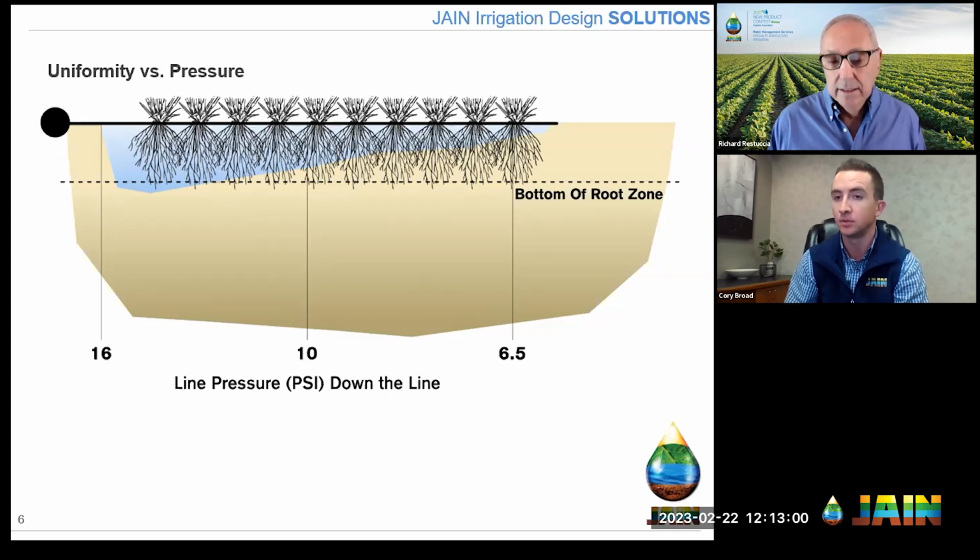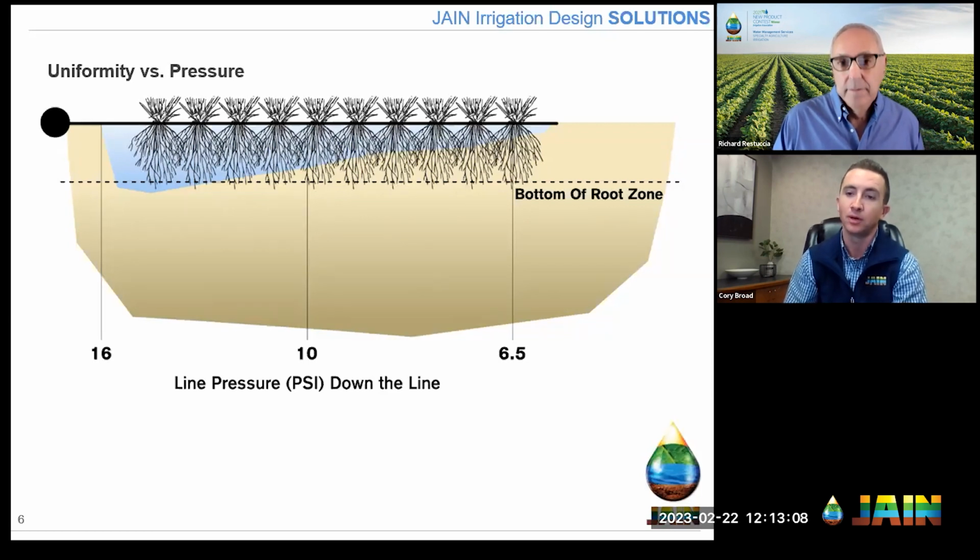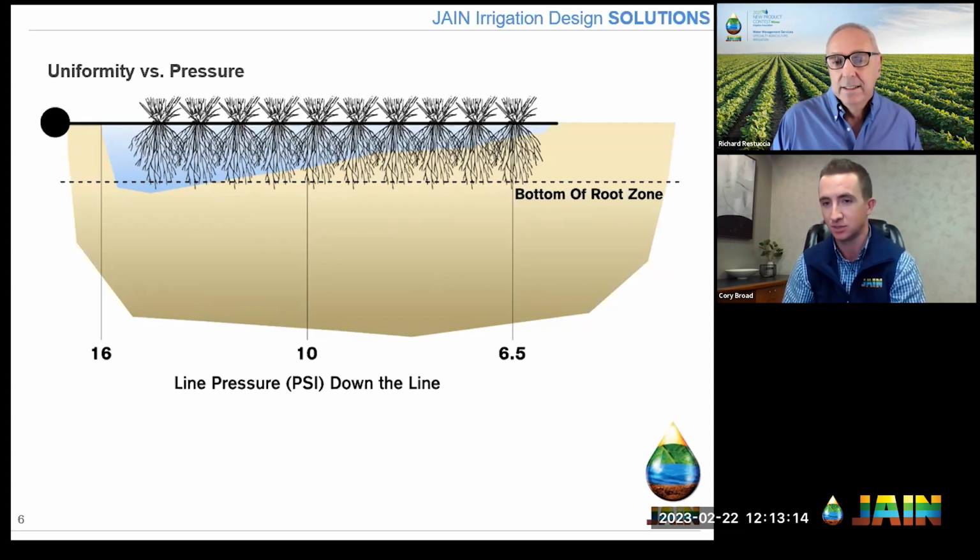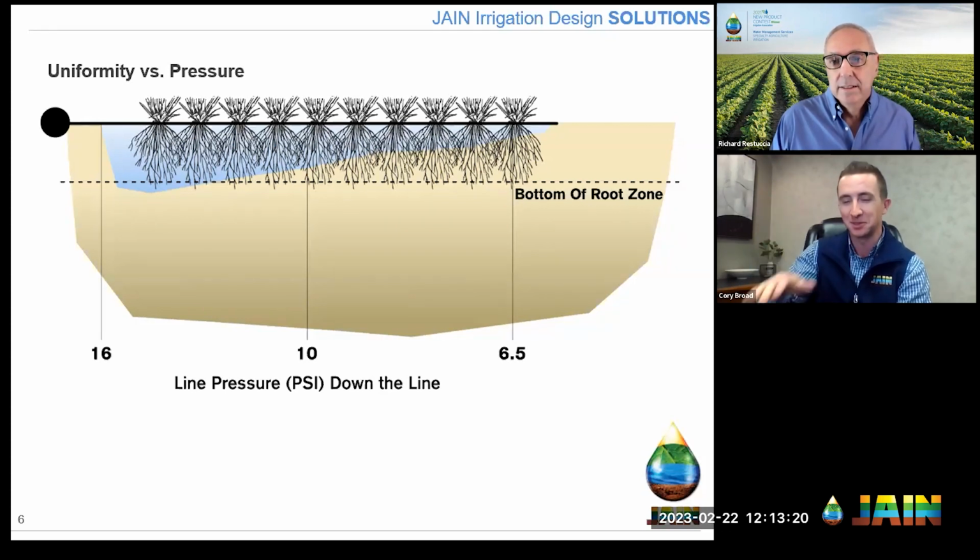And what we ended up deciding at the end is the proposed run length that they wanted, they needed to cut it in half because they told me, I want to use 1-inch tubing. And I said, why is that? And they go, because they already have that in a field next to it. And I said, okay, well then now I've been defined on what product we want to use. So that big list that we looked at earlier kind of got shrunk down to one SKU. This is the product we want to use. Okay, well now we're bound by that.